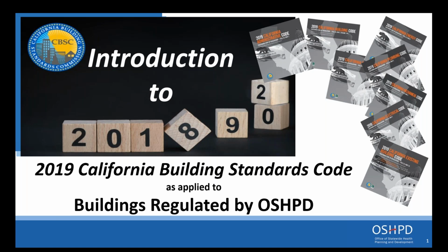Now, to talk about the CMS requirement, like Richard was talking about, that is because CMS enforces NFPA 110, 2010. And there is a requirement for facilities in seismic zones, I believe it's C, D, E, and F, to have 96 hours of fuel, or capacity, I guess you would say.